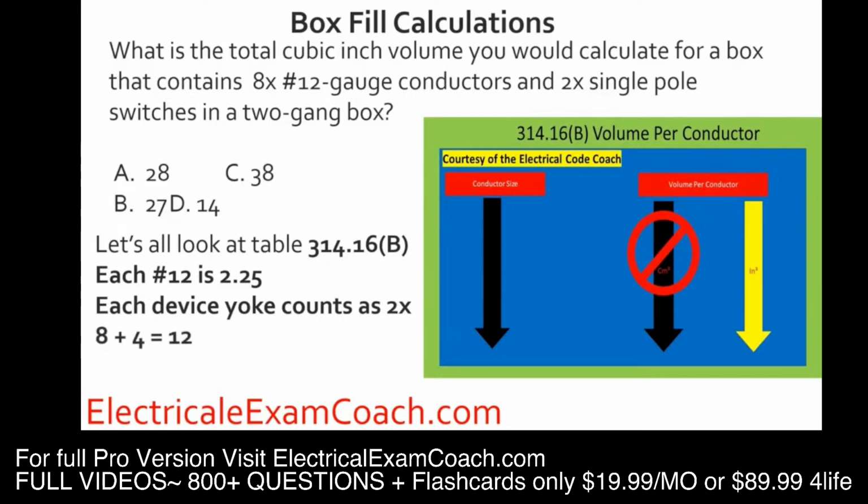We know we have 8 original conductors, and we only have one size wire, so we know it's going to get grouped with the 12s. And each one of those devices counts as 2, so we end up with 4 more number 12s, which gives us 12 12-gauge conductors. Now we take and do our math. We end up with 27 cubic inches, and we select B.